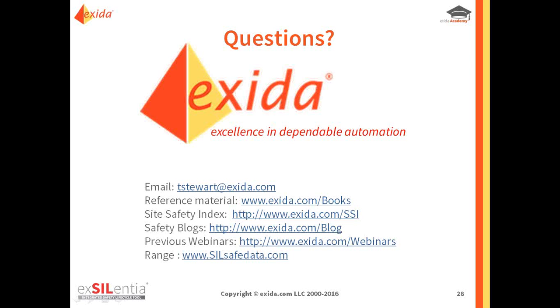Generic SIL3 logic solver data in SCRH. Is this a worst case in class? Yeah. We use predictive analytics, and we use the results to also establish the Exida generic failure rate data. The concept is, if you ask for a set of generic data, then we must assume it's the worst design. Why? Because this is safety, and that's what we have to do. We don't know how you operate, and we don't know what type of product that has and what components are inside. So yeah, we have to do worst case.